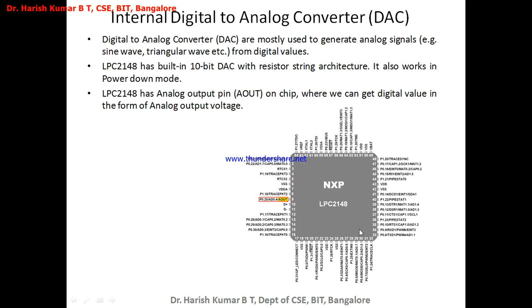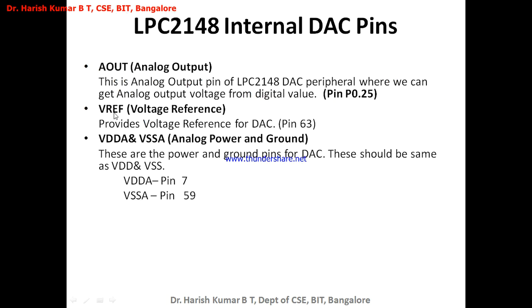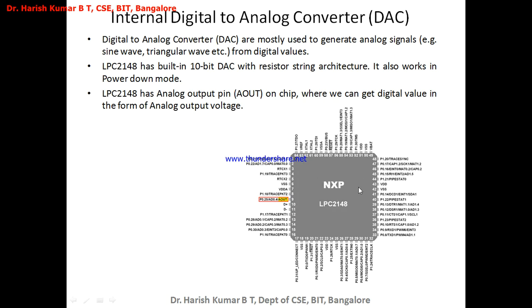You give the 10-bit digital value to the DAC, and this is the pin which will give you the corresponding analog output. It also has Vref, the reference voltage, because to the DAC built inside this LPC2148, you have to give the reference voltage.